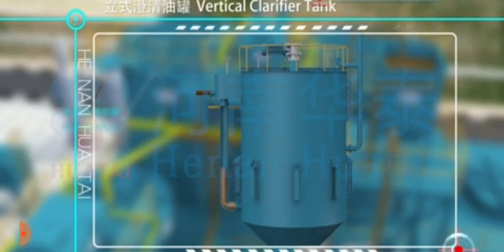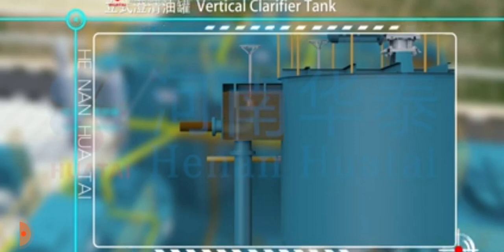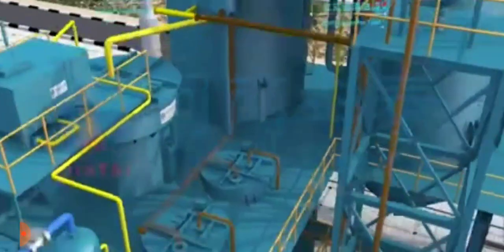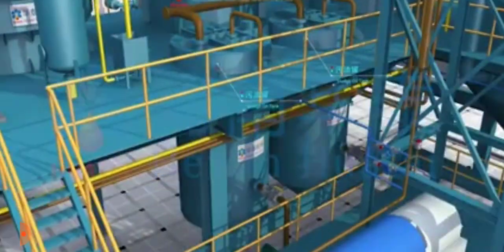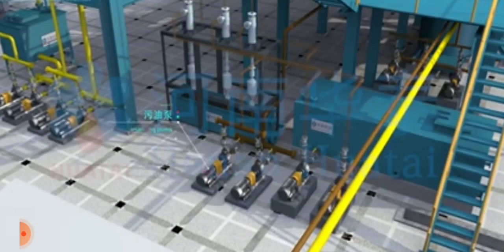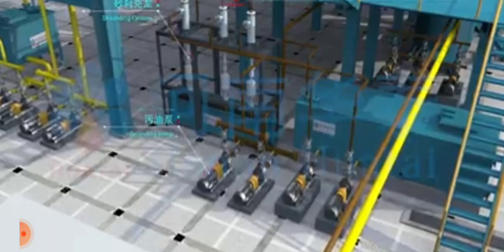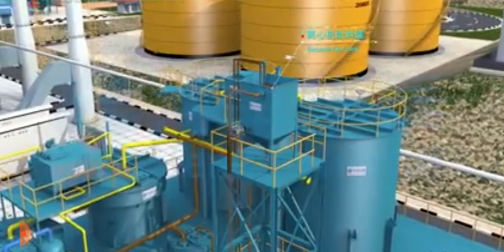Dirty oil in the vertical clarification tank enters the dirty oil skimmer from the bottom, then enters the dirty oil tank. It is conveyed to the desanding cyclone with the desanding pump, which separates hard sand in the dirty oil. Then it enters the decanter feed tank.